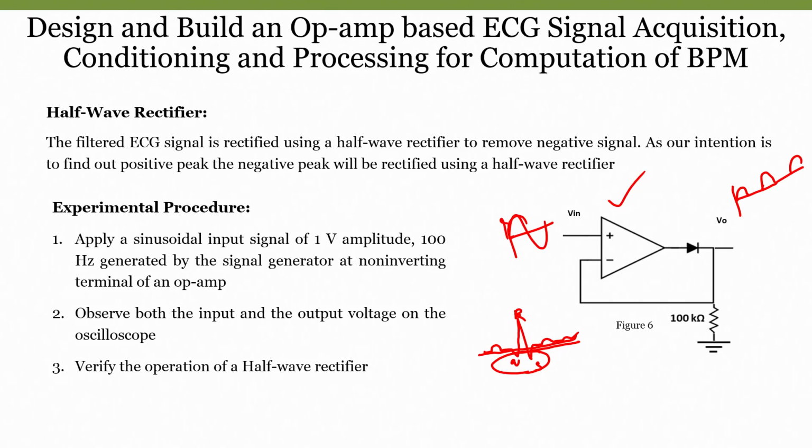As we know, if we keep a capacitor, it will charge to whatever output we receive. So, if the voltage is increasing, the capacitor charges slowly. Since we do not create any discharging path, the highest voltage that we get, the capacitor will be charged to that highest voltage value, that is good enough. So, it is easy to understand the highest peak in an AC signal.